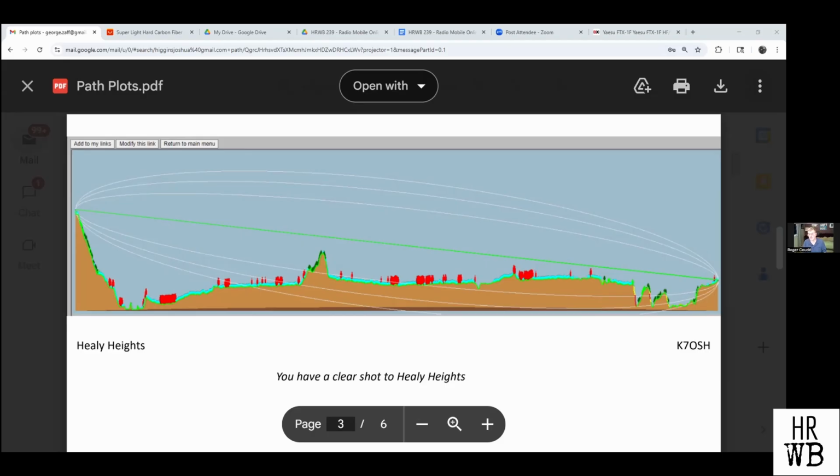This is how you resolve it. So when I put in 0.12 microvolts in my path loss calculation, that was too optimistic. Most of the time, I use 1 microvolt in UHF. But there are special cases.